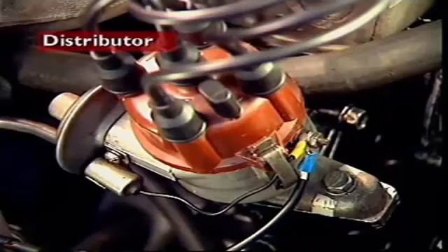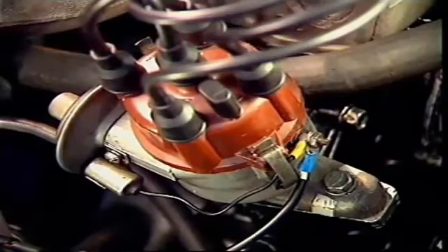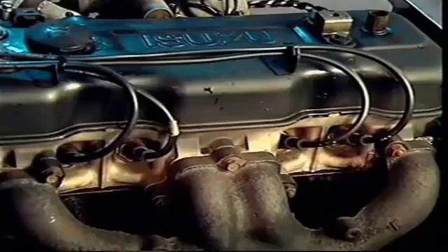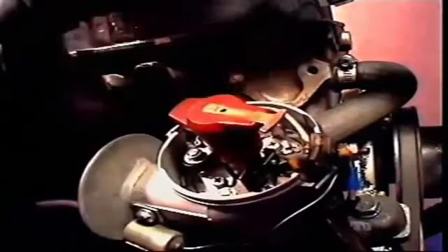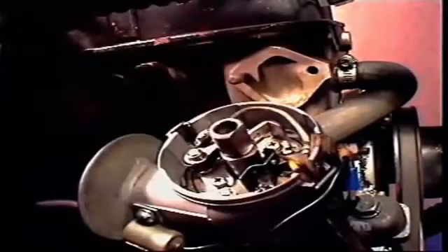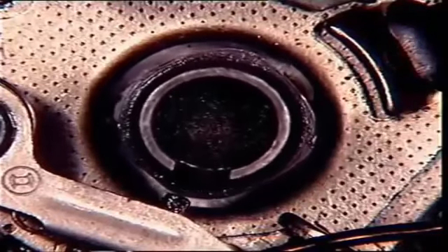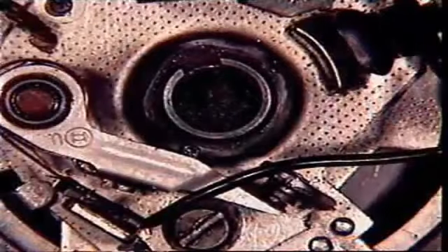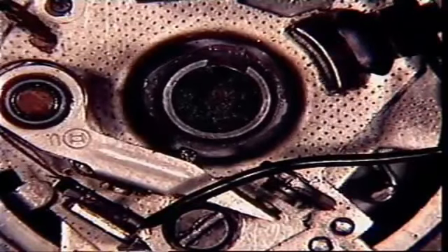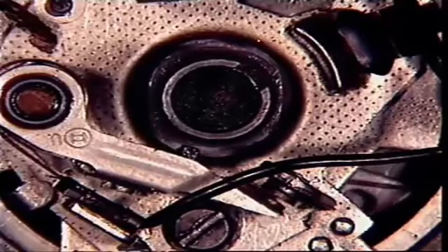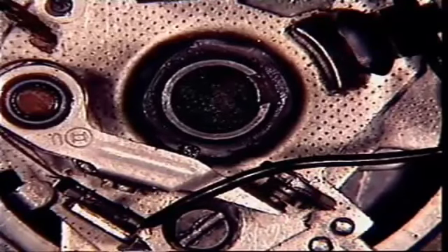The purpose of the distributor is to distribute the high-tension voltage surges to the individual spark plugs in the correct sequence and at the correct instant in time in the engine cycle. Since each high-voltage surge is triggered by the opening of the primary circuit, it is convenient to locate a single set of contacts in the distributor housing and operate them by lobes formed on a cam which is driven by the distributor shaft. The number of cam lobes corresponds to the number of engine cylinders. Ignition pulses occur as each lobe opens the contacts to break the circuit and then allows them to close, re-establishing the primary circuit in readiness for the next opening.